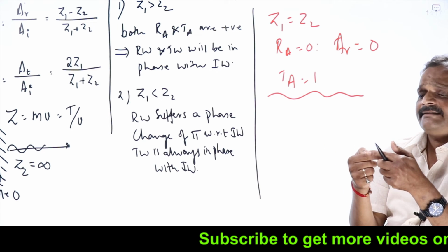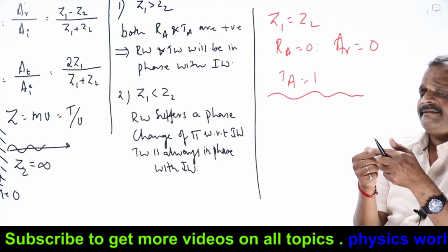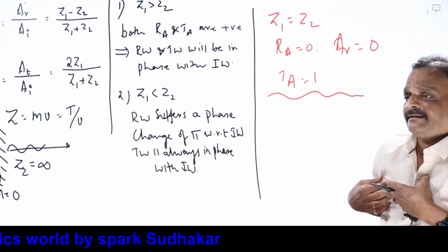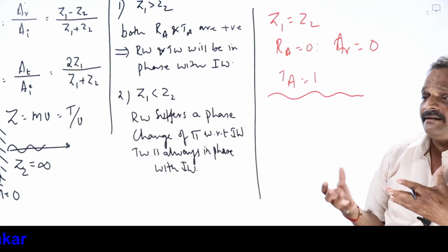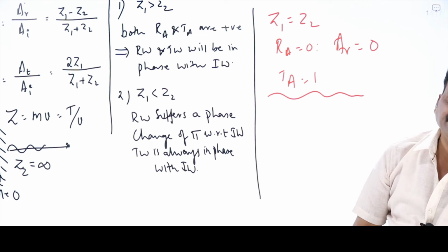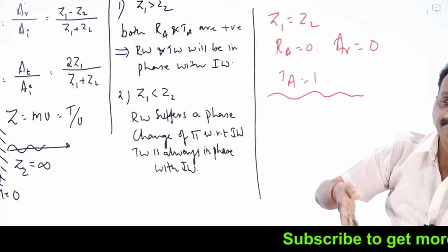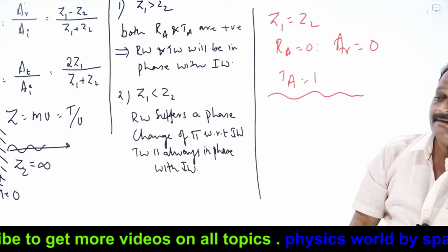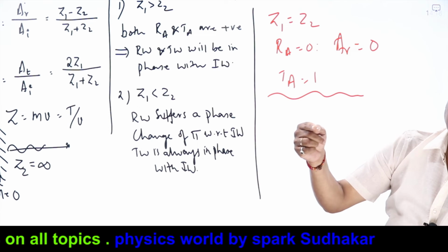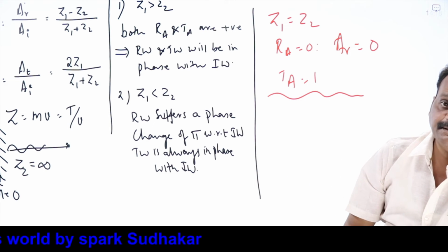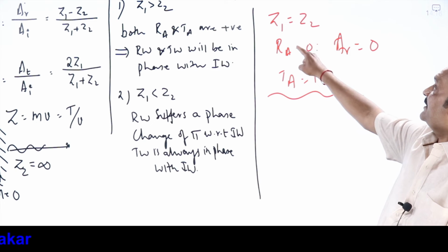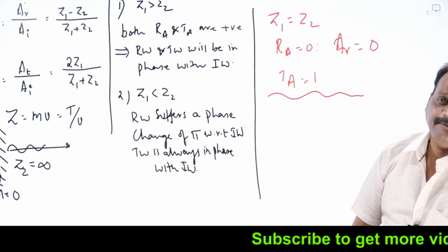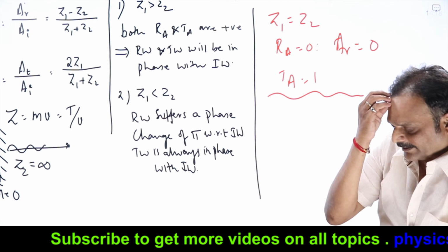That's why all devices throughout the world are made with either 50 ohms or 75 ohms impedance. If I am a company, I cannot make a TV with 120 ohms input impedance, because other cables will not match with it. Reflection will always be occurring, and the signal will not smoothly pass from one stage to another stage. So this is known as impedance matching. That's what the common collector configuration is used for in the amplifier stage, the buffer stage, for impedance matching only.